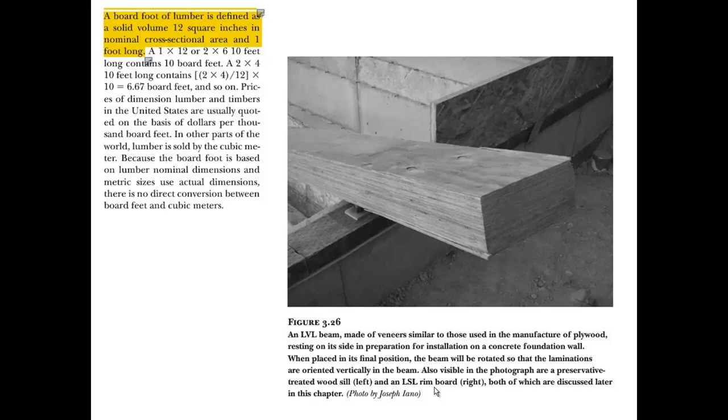Now, we don't purchase lumber as much by board foot anymore. You don't go in and say, I need 100 board feet of 2 by 4, the sales clerk would probably look at you like you're crazy. A carpenter, on the other hand, would know board feet. They may measure it. Sometimes if you're buying in bulk, you're buying by the board foot.